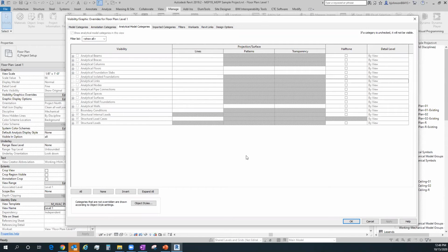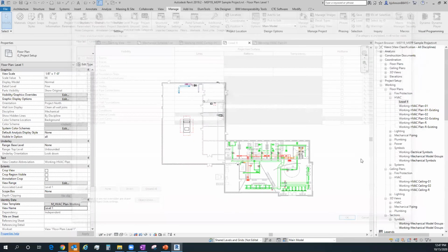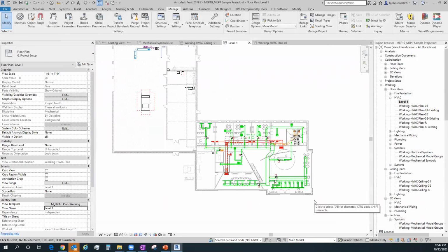So he literally had to go rebuild the template from scratch from the 2016 template, bringing all of our potential content that we needed that didn't exist in the new out of the box into that session. Then everybody could actually work fine and use the analytical properties of the structural steel. So using templates that are too old may give you corruption issues. I'm suspect of that.